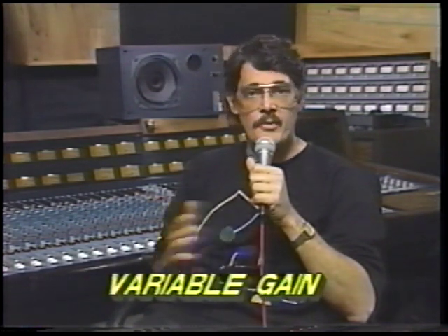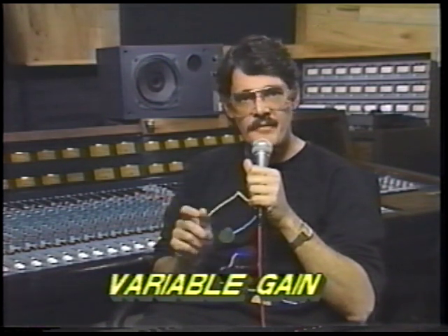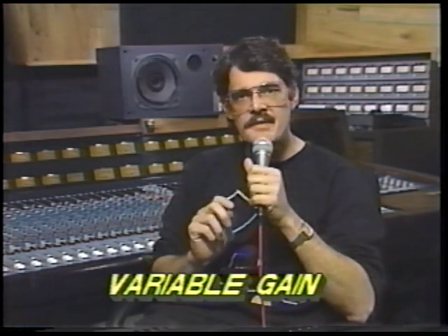Variable gain amplifiers, or VGAs, modify the dynamic range of the loud to soft of a sound. VGAs include limiters, compressors, noise gates, and expanders. They can make a loud sound less loud, or they can make unwanted quiet sounds disappear. They can reduce the attack of a sound and accelerate its decay, or they can increase the attack of a sound and make it more percussive. VGAs alter the density of the sound and affect the contrast of the affected color.